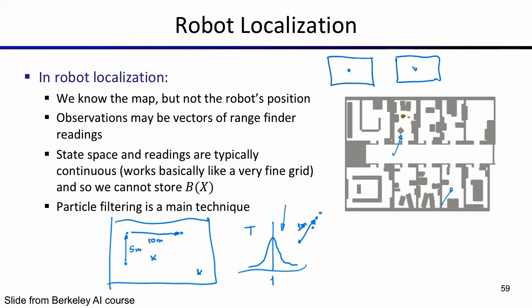And you probably noticed in the animation that we have several lines going in different directions, more or less like this. So what we have is a sort of LiDAR, a laser radar that measures the distance between the robot and the nearest object in different directions. But this sensor has a little bit of noise, so sometimes it gives us a reading that is more than the distance to the obstacle, and sometimes it's less. So there is some error involved.